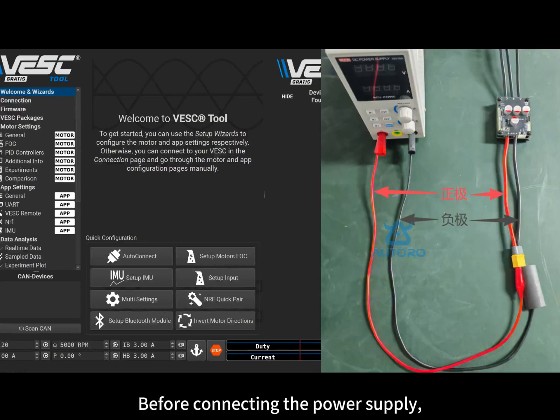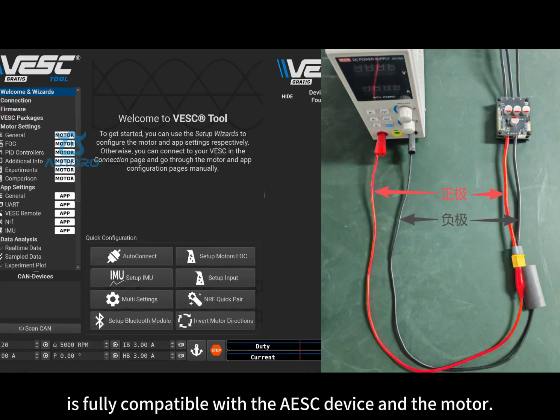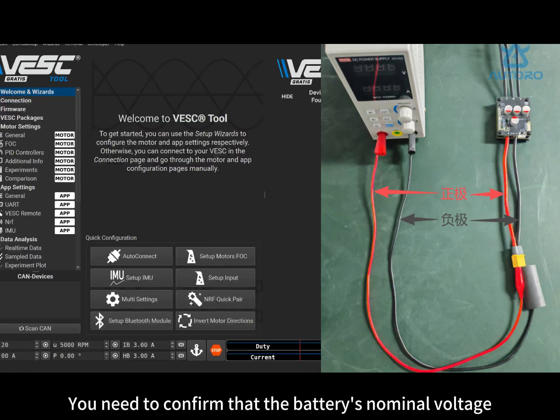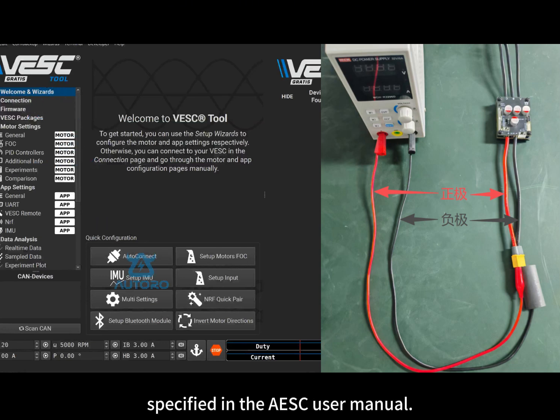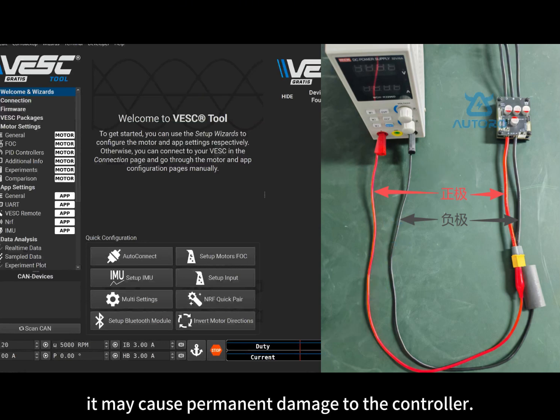Before connecting the power supply, please ensure that the power source battery you are using is fully compatible with the AESC device and the motor. The specific checks are as follows. Voltage check. You need to confirm that the battery's nominal voltage and fully charged voltage are within the input voltage range specified in the AESC user manual. If the battery voltage exceeds the maximum specified value, it may cause permanent damage to the controller.